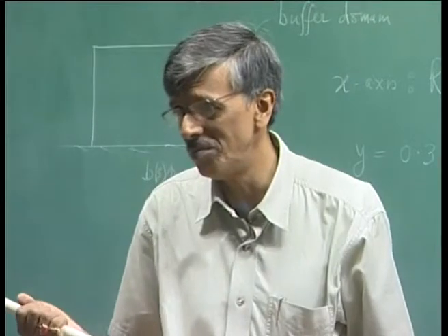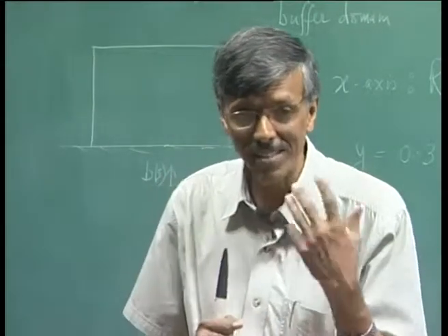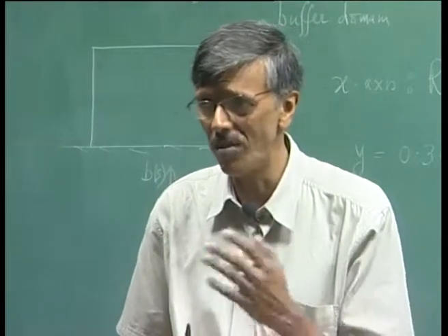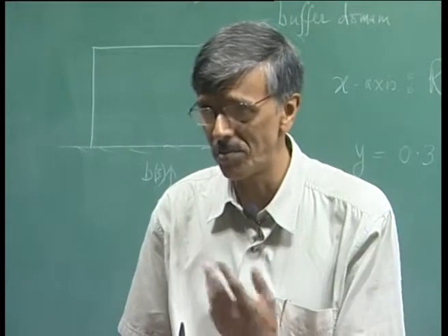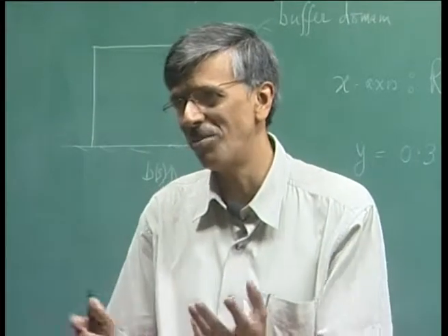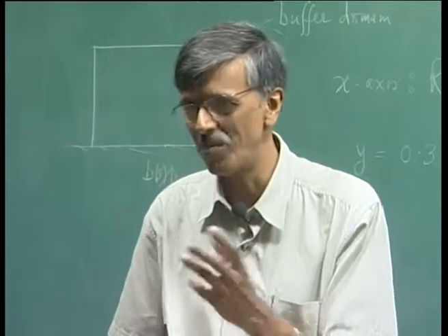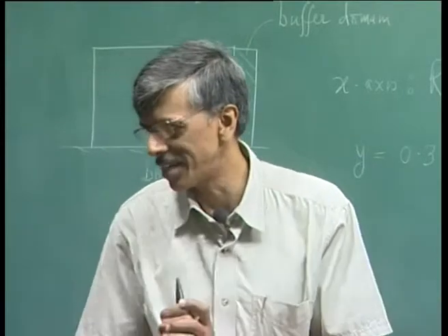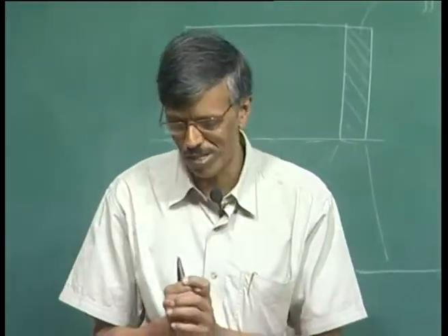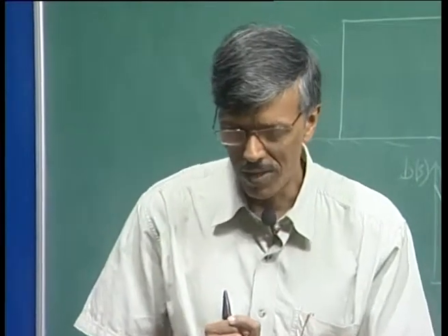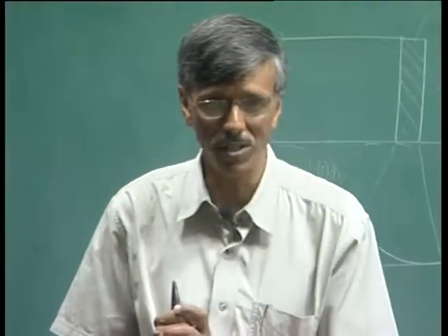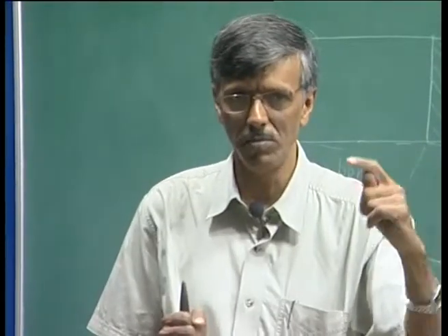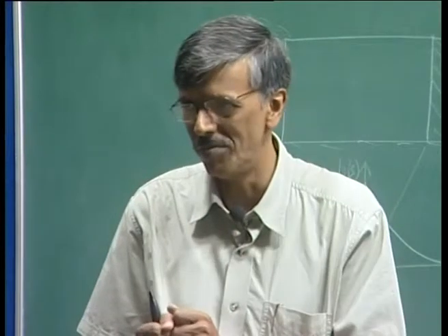What prevents us from going further? And this is exactly what Landau suggested. Landau suggested that after you have gotten the primarily unstable flow, you should study the stability of this compound flow. That is a combination of a basic flow plus a disturbance. If you look at it from the point of view of the Schubauer-Klebanoff experiment, then we are talking about what? We are talking about a basic time independent flow plus a periodic flow, because we have created a monochromatic wave.